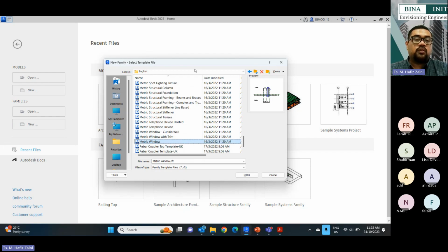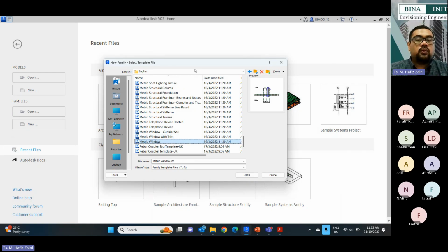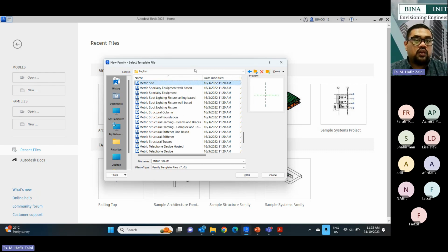Okay, some of them, for example, creating the louvers, were using curtain wall. Some of them were using windows. So it depends on your creativity, basically which base of the families you want to use to create the Revit model. But I do not recommend that you stick with the generic model.